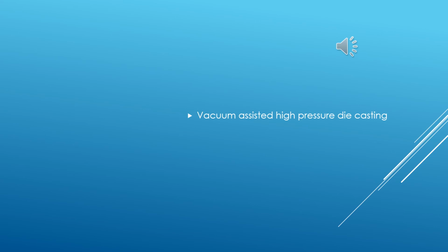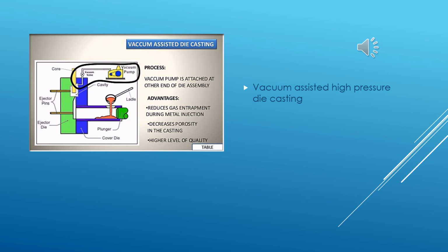By means of evacuation of the mold cavity when using a vacuum system, the gas pressure increase can be avoided. Rarely do they exceed 200 bar. A good vacuum in the mold cavity enables the metal to flow into blind recesses in complex shapes. It also allows the streams of the molten metal to merge freely without forming cold shuts.